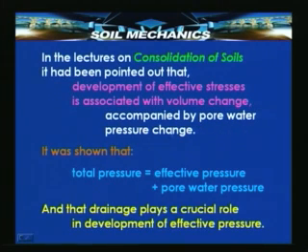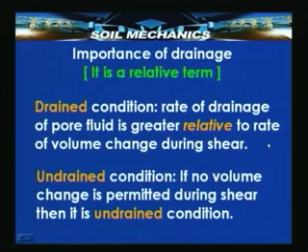In my earlier lectures, I have told that development of effective stresses is associated with volume change and pore water pressure change. Therefore, if we apply a shear force and do not allow volume change, then pore pressures will be developed. And the well known equation, that total pressure is equal to effective pressure plus pore water pressure, will be valid. Thus, drainage plays a very important role.